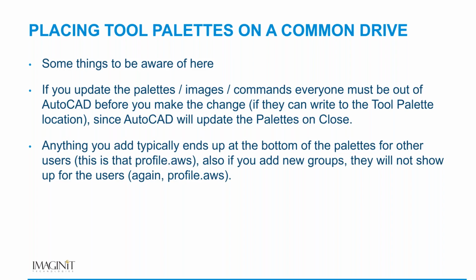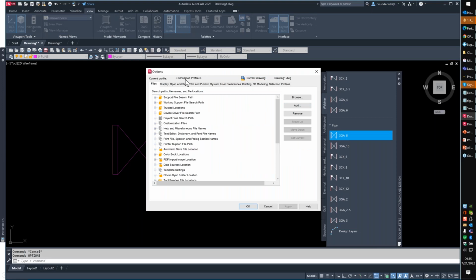And then, will changing profiles change the palette? Absolutely. Your profile here, like this is my unnamed profile, you have this tool palette path here. This may be a different location in other profiles. So as long as all of your profiles have the same tool palette location, it'll be fine.